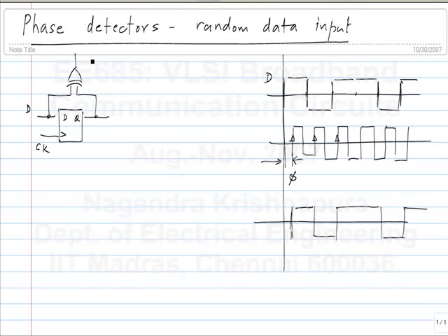So yesterday there were questions about duty cycle and so on. Which duty cycle are we talking about? Is there a problem here? In this case, the data is periodic with some period and the clock has the same period, let's assume. So in that case, we are shifting the same data, right? So there is no issue of duty cycle. It's not like two independent signals which have different duty cycles and you have an issue with phase detection.